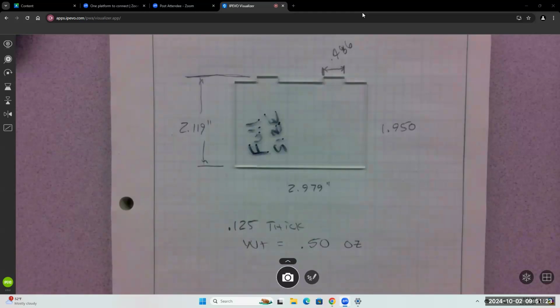Exactly. Pressure equals specific weight times depth, which we'll do more on later. Since neither of these has an exponent, this is a linear equation. That means as you go deeper, for every increase in depth you have an equivalent increase in pressure.